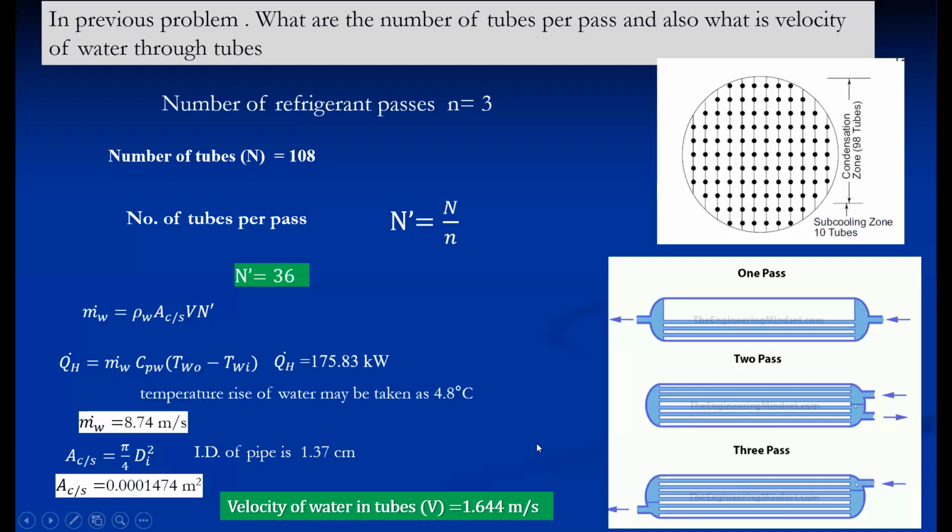It is recommended that velocity should not exceed 3 meter per second. So it is also necessary to check the value of velocity of the flowing fluid. It should not exceed 3 meter per second, because if it exceeds that value, generally the pressure drop is considerable, and that is called the penalty cost. So the penalty cost is greater than the benefit, that is the enhancement factor. Increasing velocity leads to an increase in the heat transfer coefficient, but the golden mean should be there.